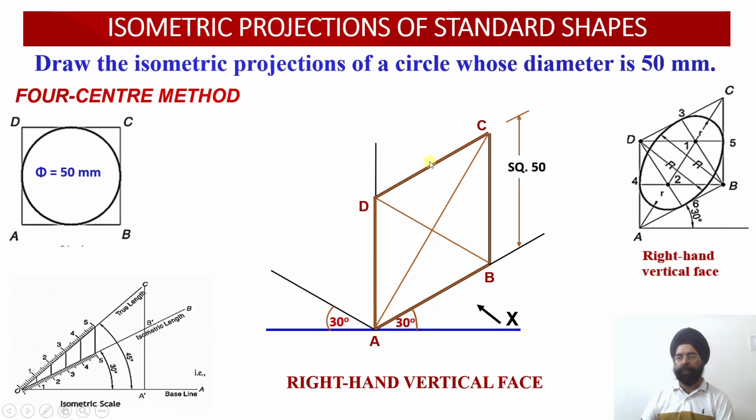So we have to obtain the midpoints of all the four edges of the square. Once we obtain the midpoints, from the two corners, as we did earlier, from this corner draw the construction line joining the opposite midpoint over here. This is named M1. So B1M1 is a construction line which joins B1 with the midpoint of the edge CD. Similarly, from B draw another construction line which will join the midpoint of the edge AD.